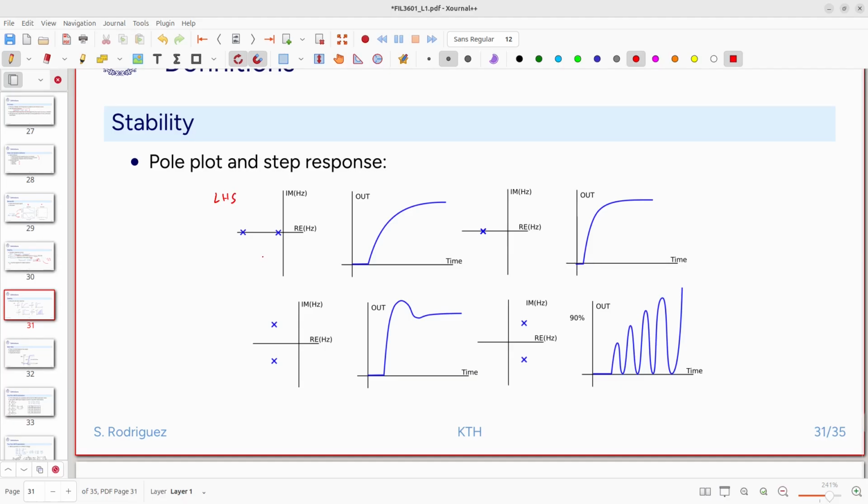When we convert this system to the time domain and we use a step response, typically we characterize this using a step response. That means that we send a step to the system. We will see that a stable system basically does the following thing. They are exponentials that are decaying until it stabilizes at a particular output voltage or current. We might have complex poles in the system. The complex poles we also characterize using the step input. The output will look something like this.